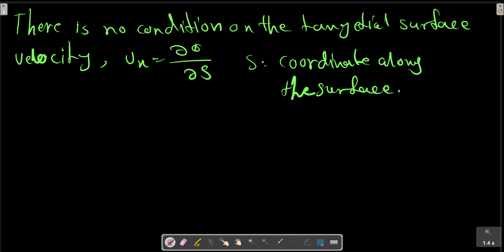Occasionally, the problem involves a free surface for which the boundary pressure is now equal to Pa, usually a constant. The Bernoulli equation then, we have a relation for the Bernoulli equation in momentum, which was d phi over dt plus the kinetic term.